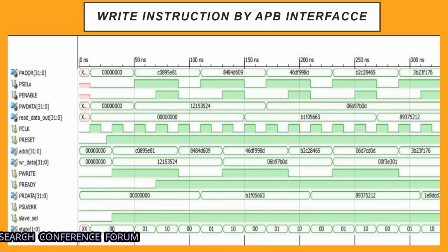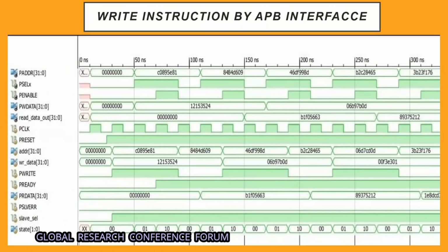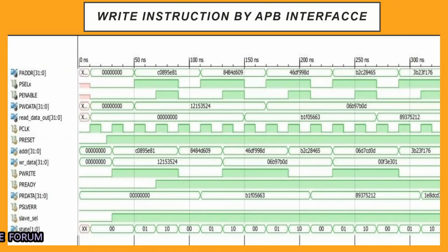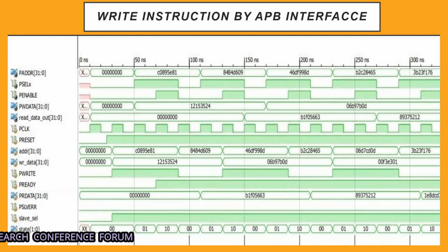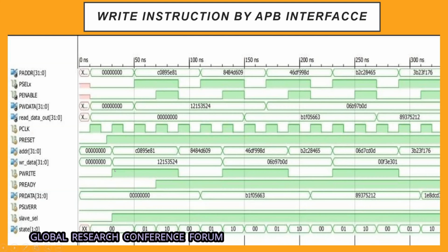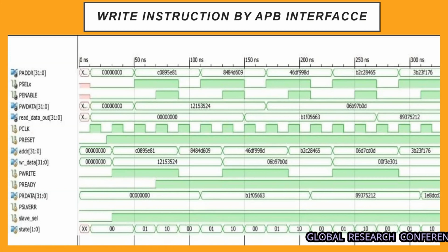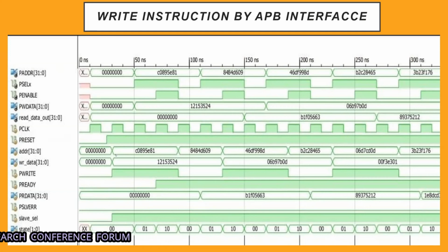This is the waveform that has been generated. It shows that we have successfully verified our design and that it matches the waveforms given in the specification sheet. We have tried a bunch of write operations here. Ignoring the initial clock cycle, as I'm applying the reset at 25 nanoseconds, our states are continuously changing per clock cycle.